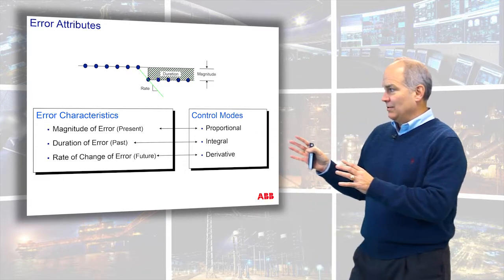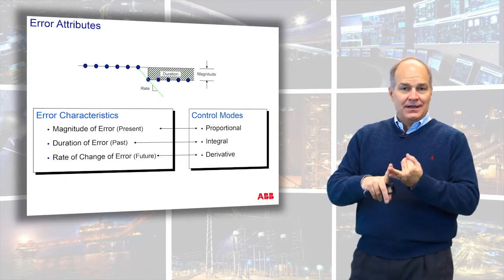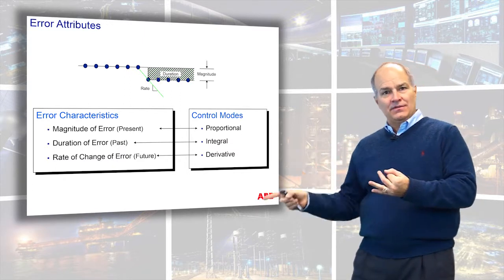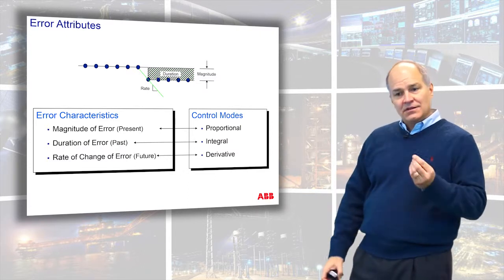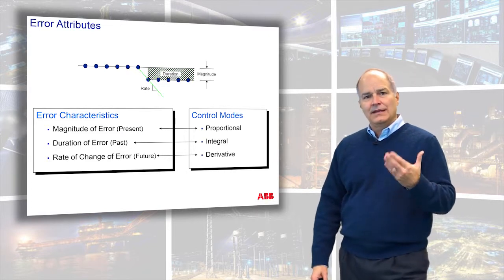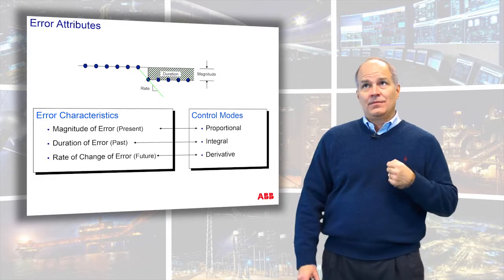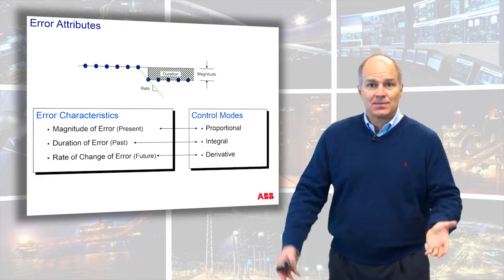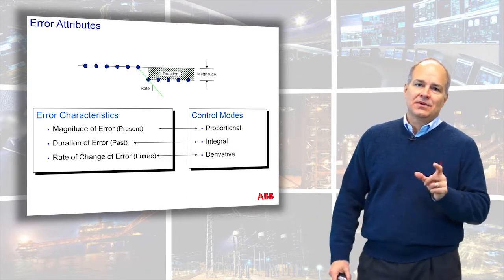Now what we're going to go through is understanding the interactions. We're going to start with proportional and integral by themselves, and then we'll add derivative later, because derivative really isn't used that often. So let's understand the P and the I. Things that you have: they talk about integral time, integral gain, reset time, repeats per minute, minutes per repeat. What in the world is all that stuff? Hopefully this section will answer that.